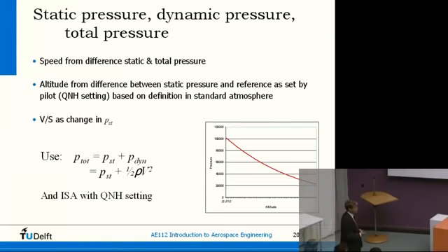The altitude difference. You measure a pressure, but you do not know what the pressure at sea level is normally. You don't have an instrument to measure that, and this varies during your flight. So that's why normally we assume a standard atmosphere, and at sea level we assume the standard level during our complete flight, and that's because all the aircraft take the same reference level, which means that relative to each other we always have the correct altitude or altitude difference.